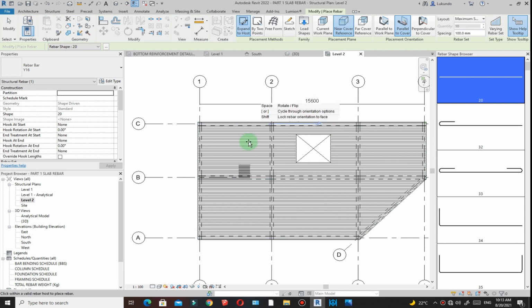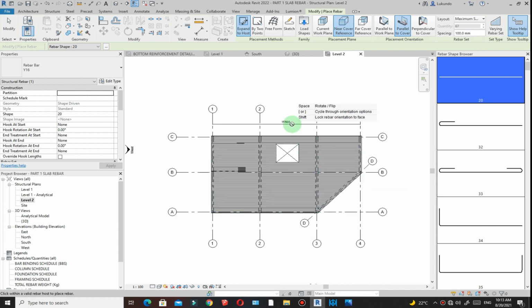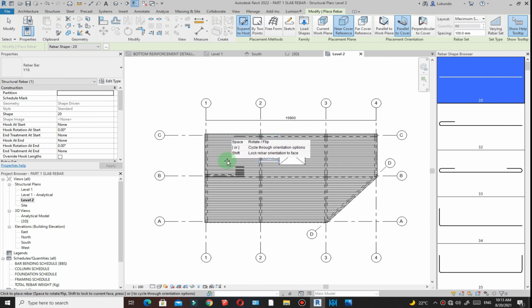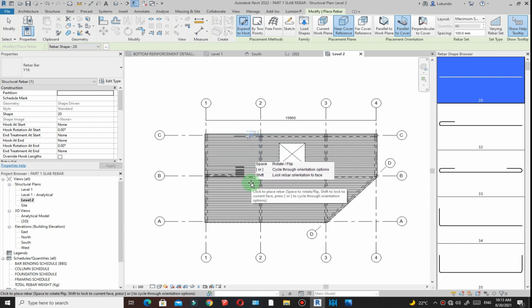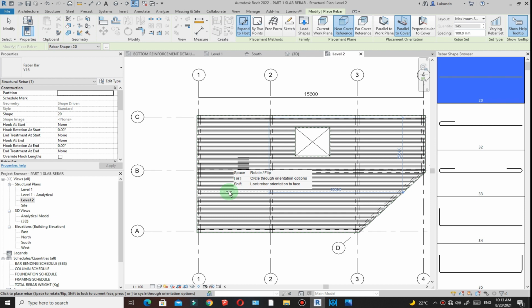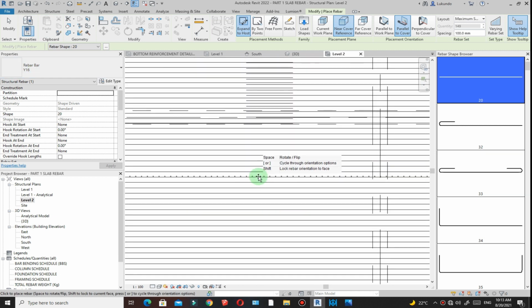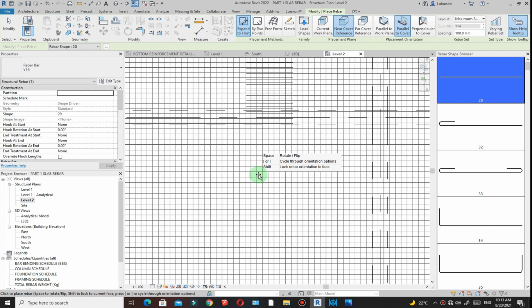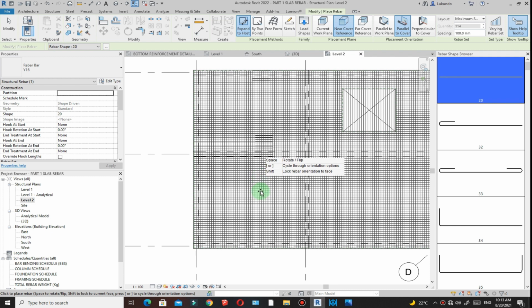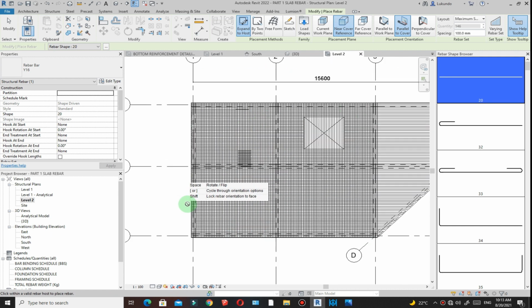Make sure that the rebar that you are modeling here, even the lapping points, the top rebar and the bottom rebar, is according to the design. But I want to show you the workflow of how you are supposed to model the rebar and also detail. Okay. So from here, I'm just going to maintain Y16. What I can do, I can just hover the cursor there, then space bar. You see that it's now perpendicular there. Click there in the short span. I have the rebar right there.